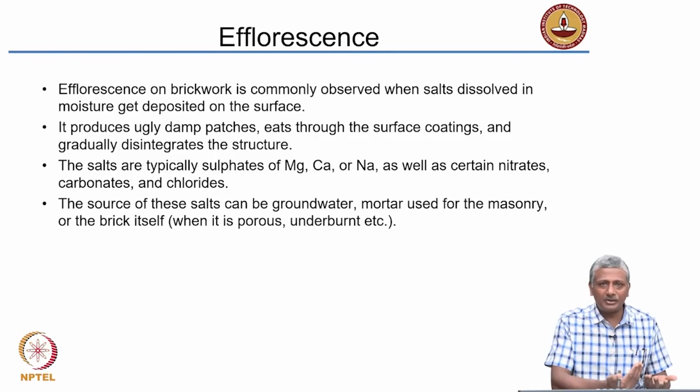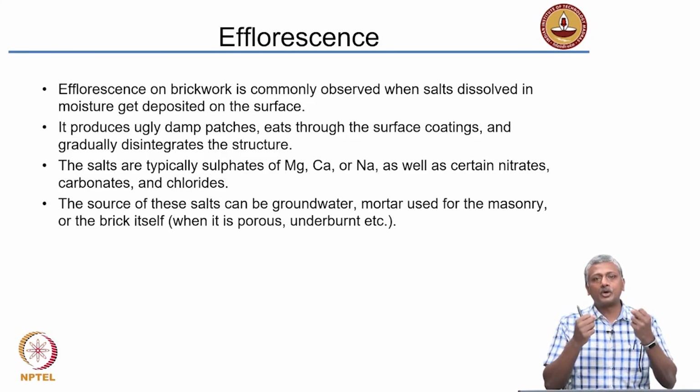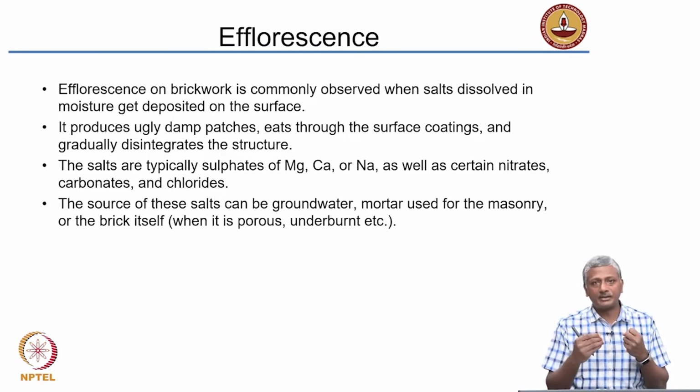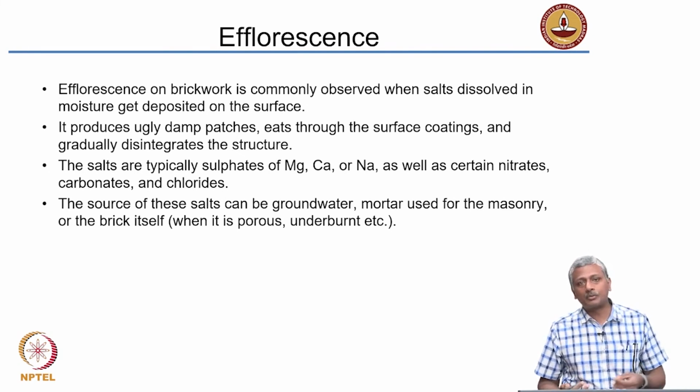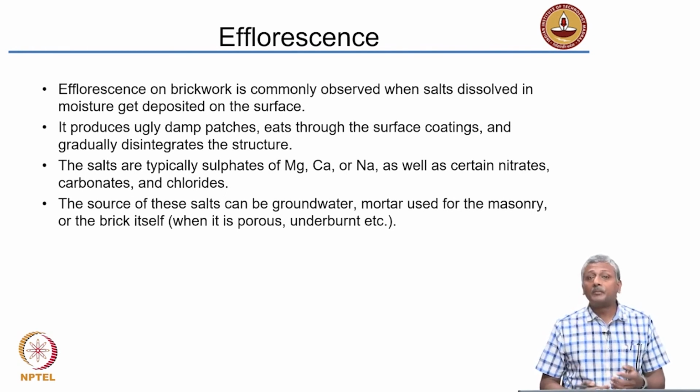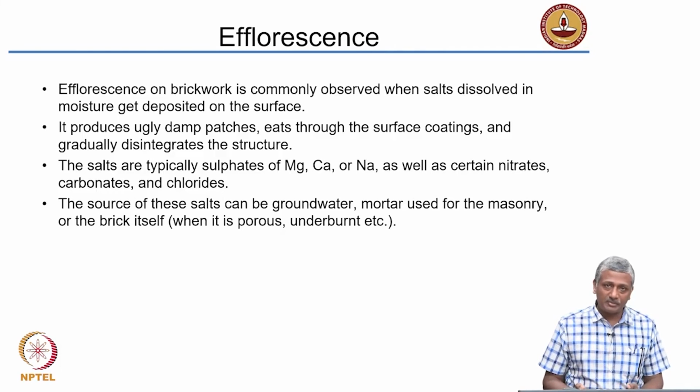Why are the salts getting into the brick in the first place? Because bricks are absorbing moisture from the outside. Are salts present inside the brick? High possibility is there because of the water that is used to mold the brick, because of the clay that was originally used to manufacture the brick, that may itself have some salts in it.